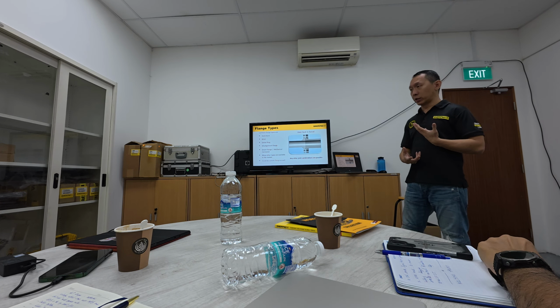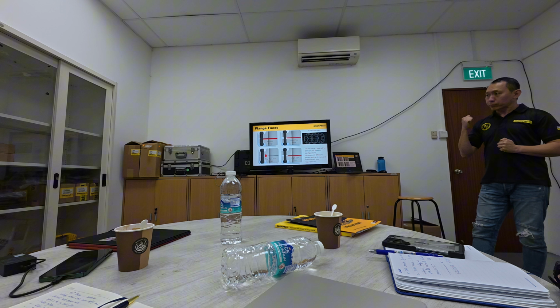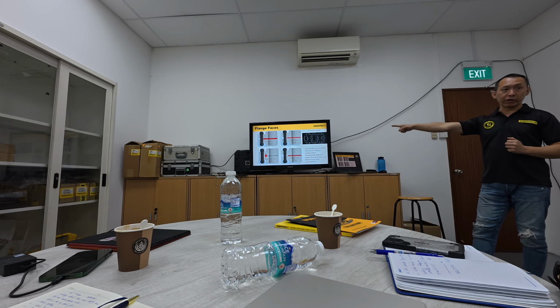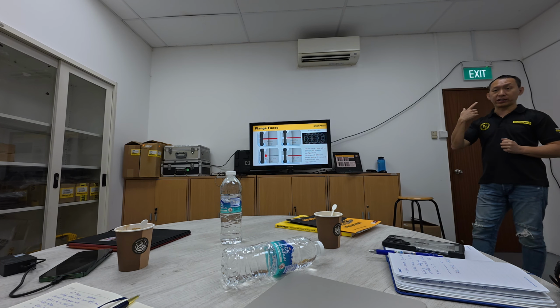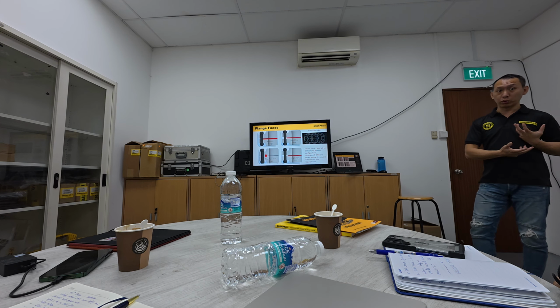Okay, because with different sealing, gasket sealing stress is different, and of course different workload requirement. So for the different types of contact area, you probably need different sealing stress and then of course different workload. So your setting of the tool will be different for each flange type. So if the customer doesn't tell you what type of flange, it's very difficult for you to advise on what type of tool to use.